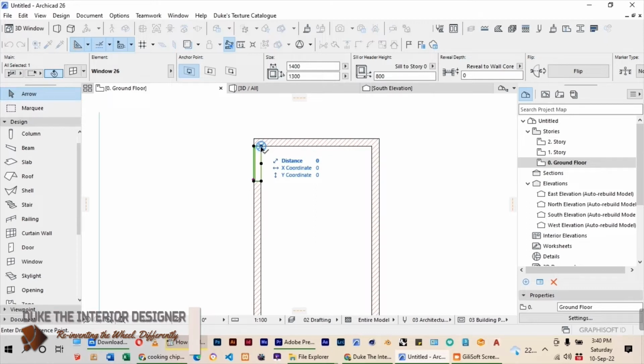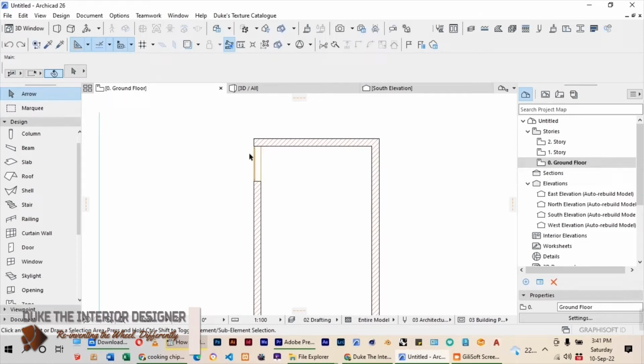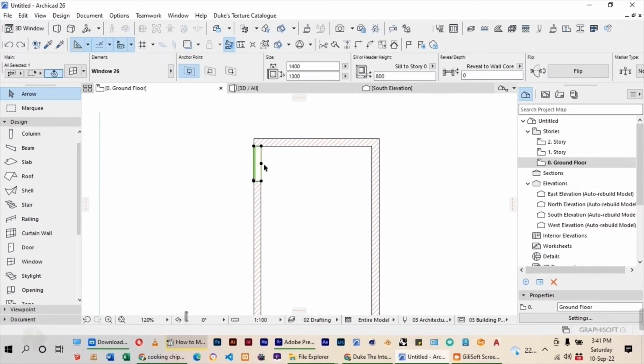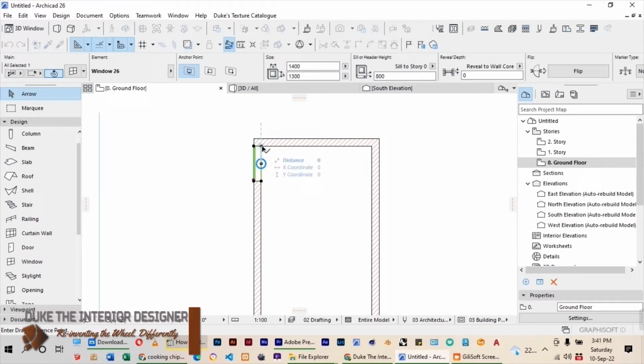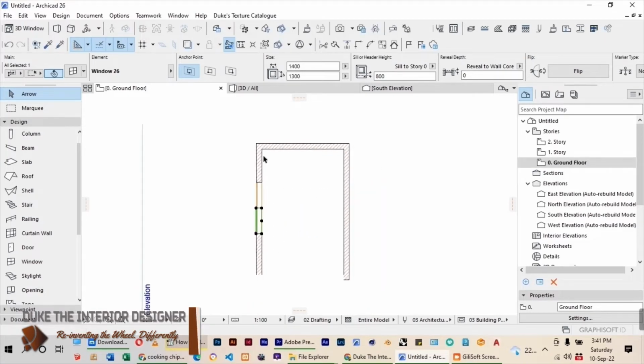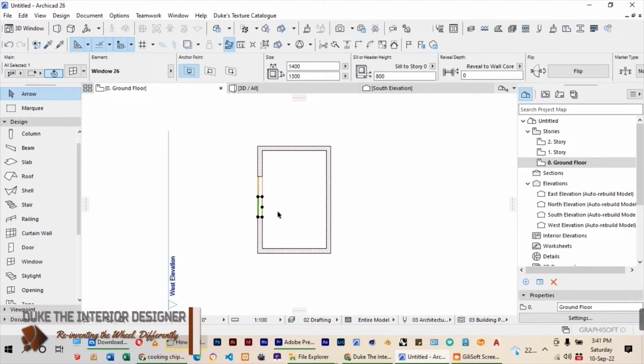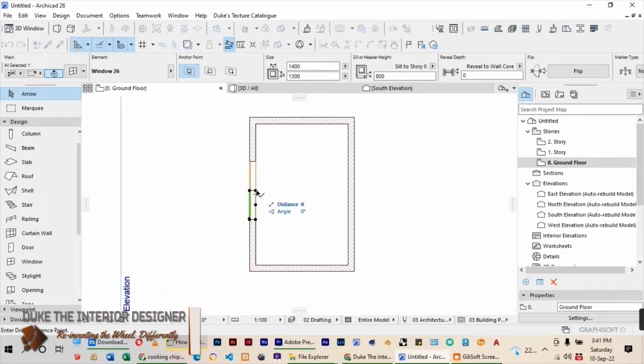So when I'm doing this, I need to move this window from the wall, so I need to offset by 1800, that is Control D, 1800, Control D copy for a copy, first put it there, then offset this, Control D, that's move, by 1200,